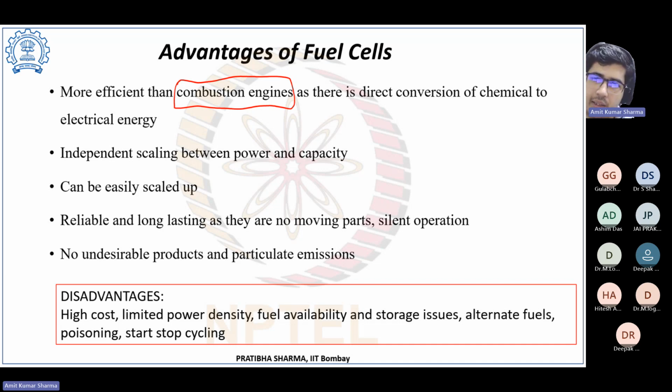For the fuel cell, you can maintain the temperature by increasing the flow of air or oxygen, so your oxygen outlet stream will be heated. Either you can put heat exchangers on the downstream side, where you get your anode and cathode outlets, and recover heat. No issue with that.